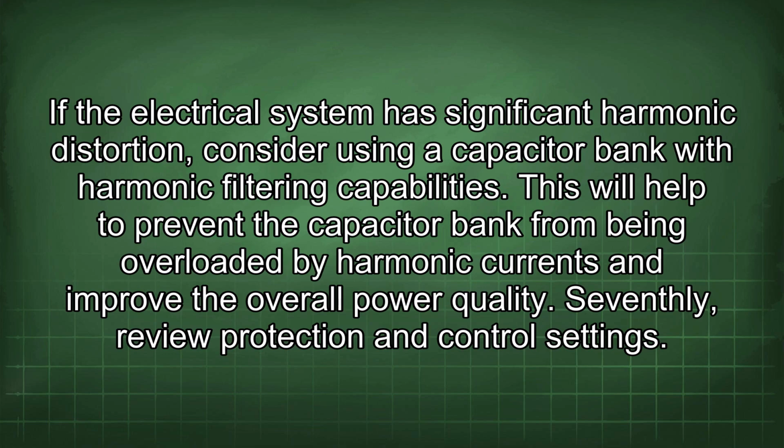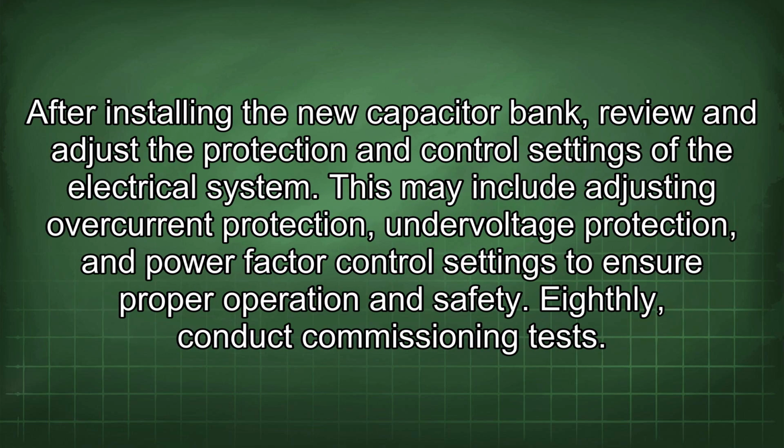Seventhly, review protection and control settings. After installing the new capacitor bank, review and adjust the protection and control settings of the electrical system. This may include adjusting overcurrent protection, undervoltage protection, and power factor control settings to ensure proper operation and safety.